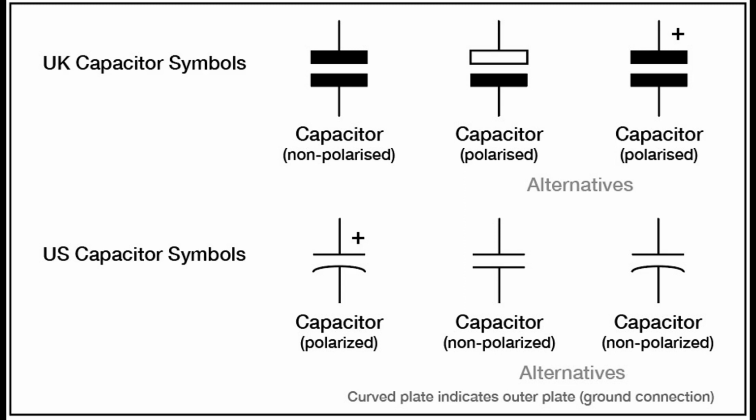Electrolytic capacitors are utilized in PFC circuits to store energy and help shape the input current waveform. Switching power supplies. Electrolytic capacitors are used in switching power supply circuits to store energy, regulate voltage, and reduce ripple currents. They contribute to the overall efficiency and performance of the power supply.